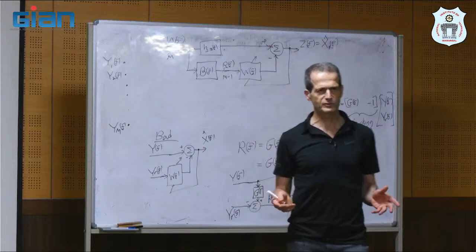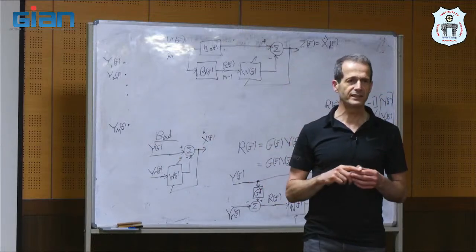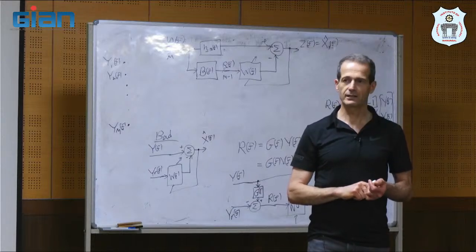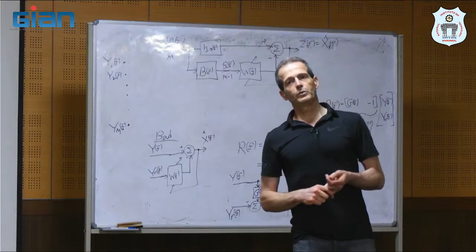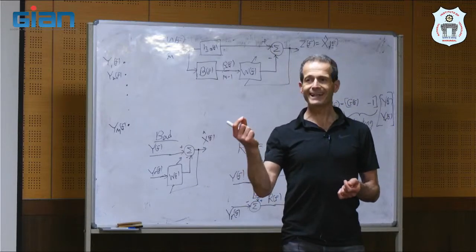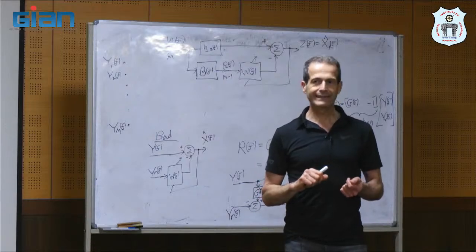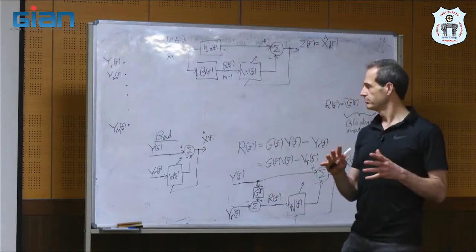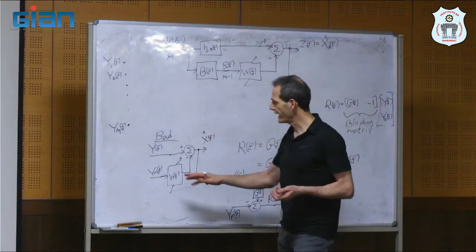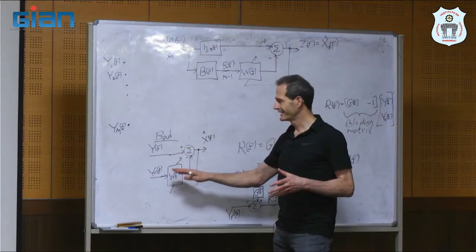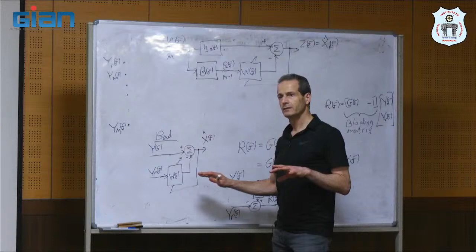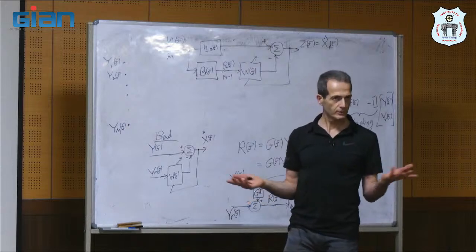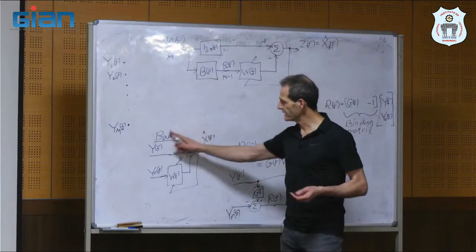Okay. What is the noise? We have different types of noise, but what is the main interference? Exactly, the mother's heart rate. So what do you need to do? You can add another sensor, another microphone, and put it next to the heart of the mother. So maybe it will have only the reference, only the heart rate of the mother, and the heart rate of the baby is negligible. Okay?